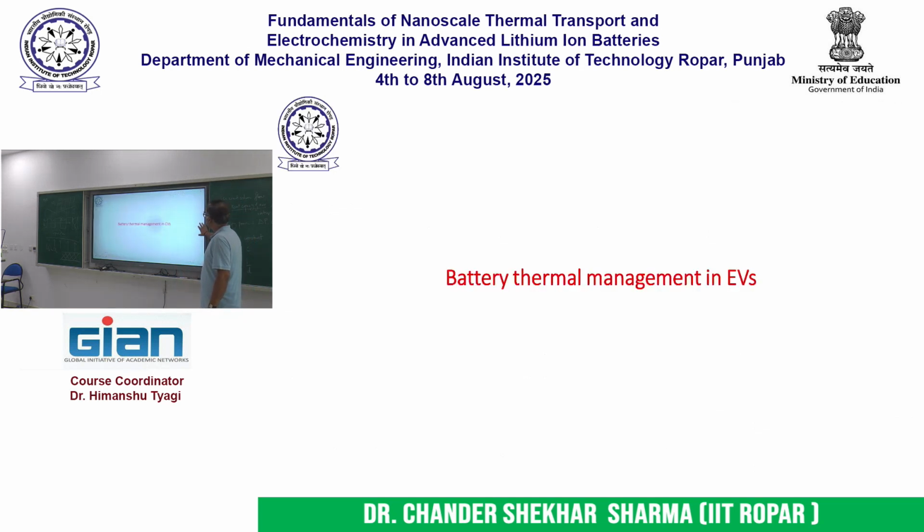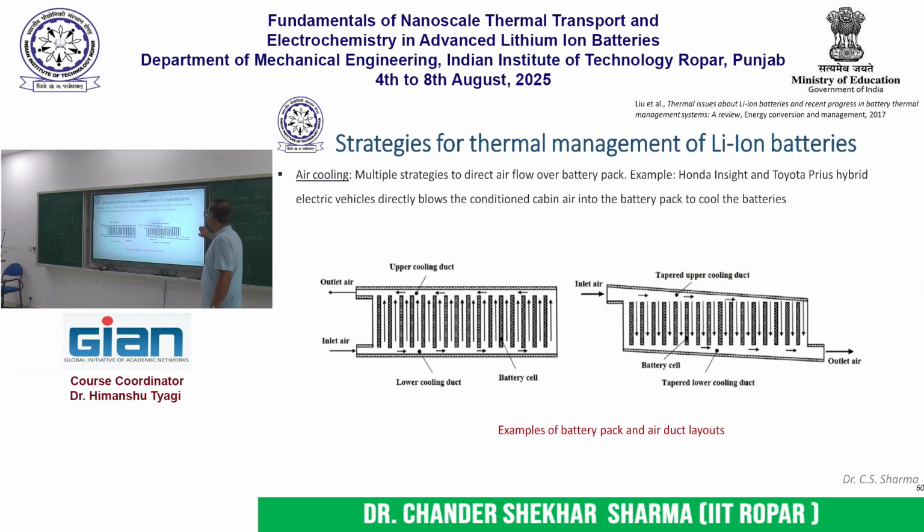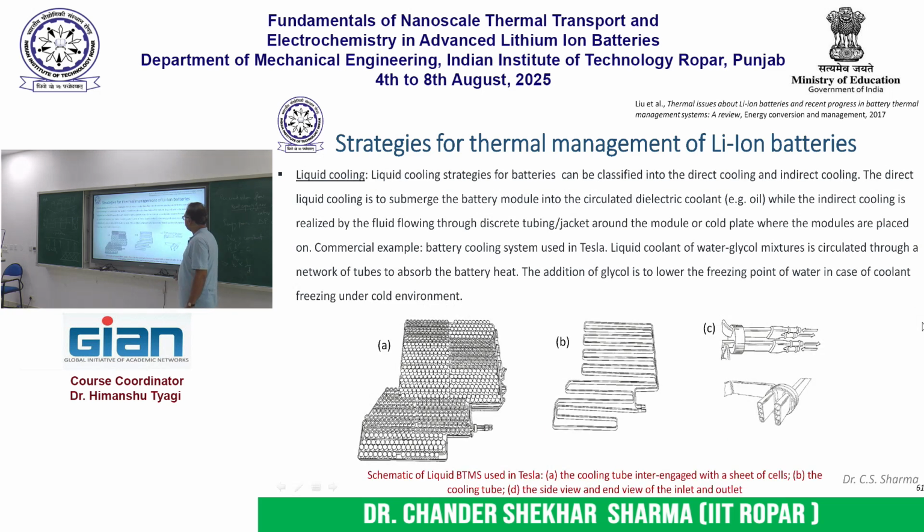Okay, so I will close this lecture by a short discussion on battery thermal management in EVs, the electric vehicles. Okay, so in electric vehicles, the batteries all need to be maintained right within the required temperature zone. So various strategies are being used, and the strategies that I have mentioned, all of them or a combination of these are being tried. For example, single phase cooling, you can have air cooling that is going through the battery packs. Okay, then you can have liquid cooling.